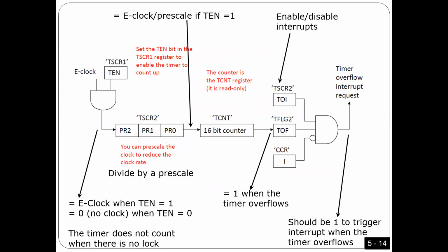Okay. So this is just a diagram I'm explaining here. Here, this is 24 megahertz. In this picture, I put everything together. This 24 megahertz goes this way, right? And this is the pin I told you to run or not run. If you put 0 here, the output here is 0. This will be the input of the counter, because the counter should count as long as there is a clock, right? If there is no clock, the counter is not going to count.